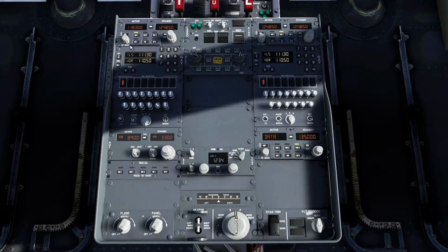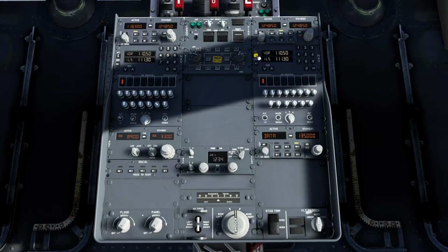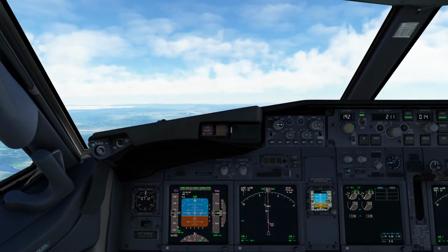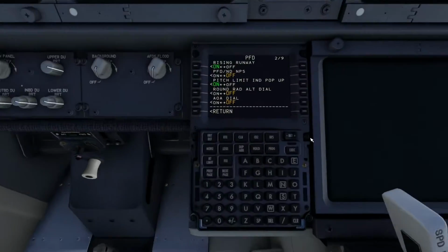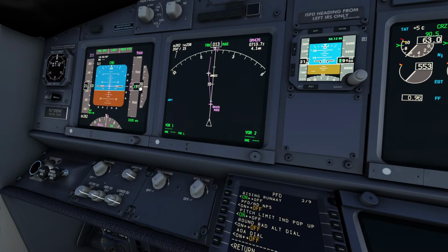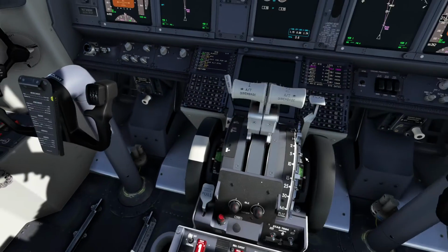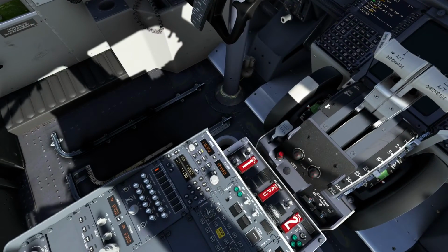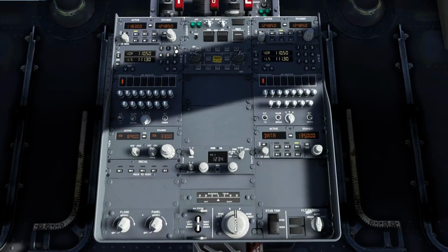So anytime you take the ILS out, you will see, let me go back to this one, you will see that they didn't remove the ILS. Yeah, I didn't remove because I chose another ILS frequency. So forgive me, I want to take 115.95, just an example here. And once again, 115.95. My mistake.